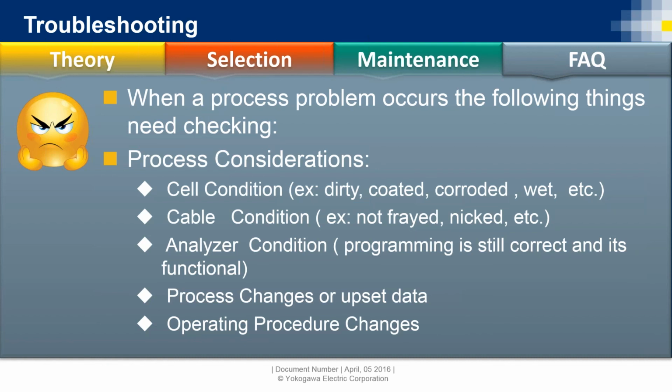If you get a brand new sensor, you stick it online, and you've put in that cell constant. Remember, with contacting conductivity, you have to put in a cell constant, a multiplication factor: 0.1, 0.01, 1.0, 10.0. If it's off by a factor of 10, it's a good indication that there's something wrong with how I programmed my cell constant. And it could be as simple as the analyzers normally auto change from micro to milli Siemens. If we put in a cell constant wrong, it could be that, and that's most commonly what we see, and most of the time the problems are at just startup.